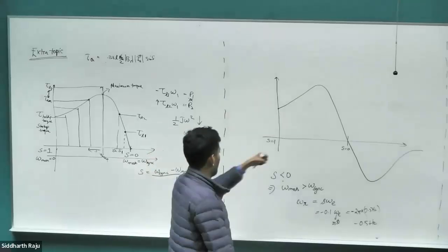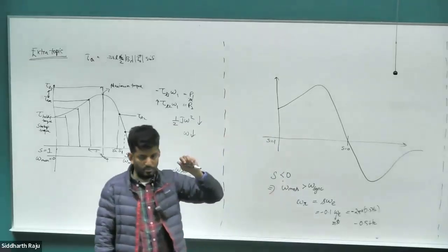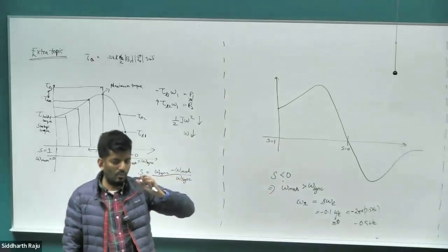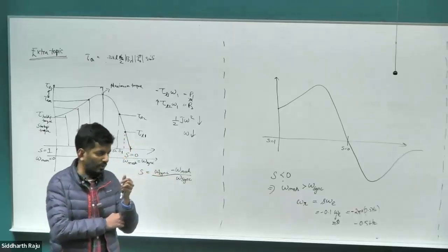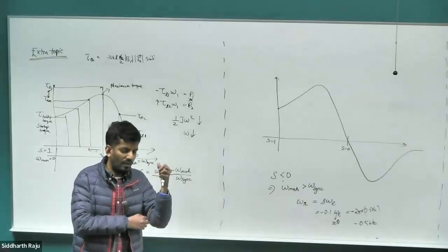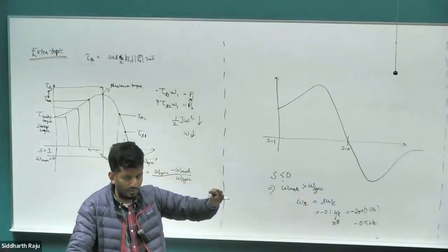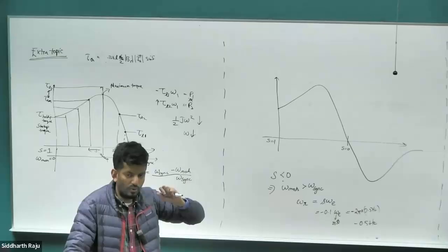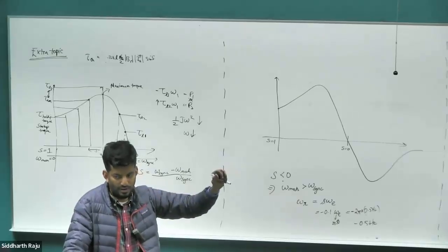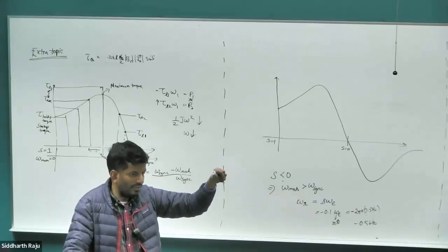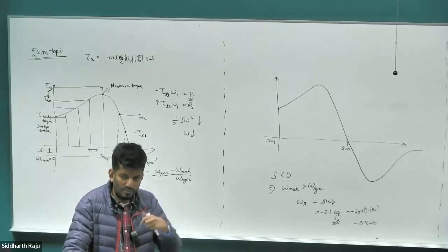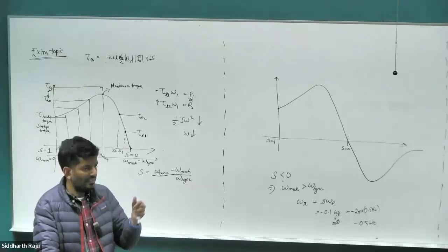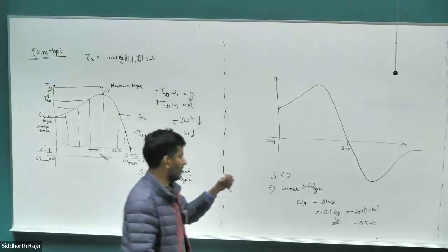So the rotor is rotating faster than the EMF space vector, but we know in an induction motor at steady state, all the space vectors have to rotate at the same speed. And how do we do that? So let's think of a case where a train is going at 100 miles per hour, and another train is going parallel to it at 105 miles per hour. Now, if someone inside the train going faster at 105 miles per hour runs in the opposite direction at 5 miles per hour, then they would be exactly at the same speed as the first train.